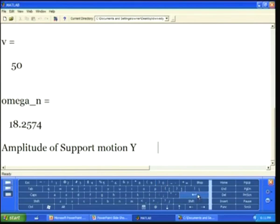So, when this velocity is 50 kilometer per hour, for root over k by m you can see omega n equal to 18.2574. Now, let me give the amplitude of support motion, let the amplitude of support motion be 0.05 meter.